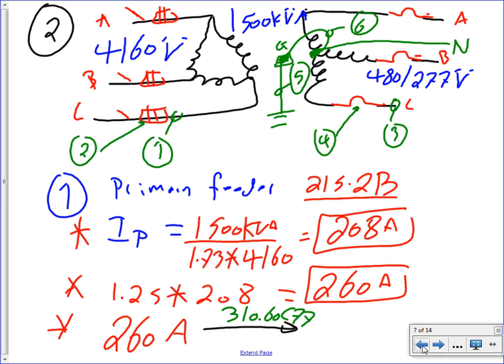For the 13.8, where it's going to start and stop, there are logical reasons. When they bring their 13.8 to your building, there's a demarcation point. They have to put the demarcation point somewhere. They can put it in a box outside, or in the primary of the transformer, or somewhere else. But for the time being, I'm assuming we are installing these and the demarcation point is right in here. From here, Excel; from here, us.